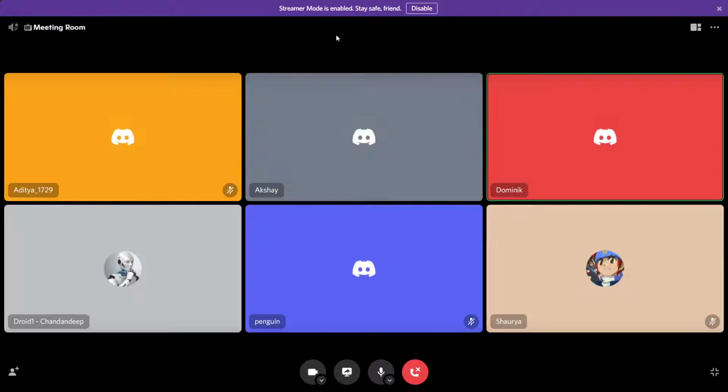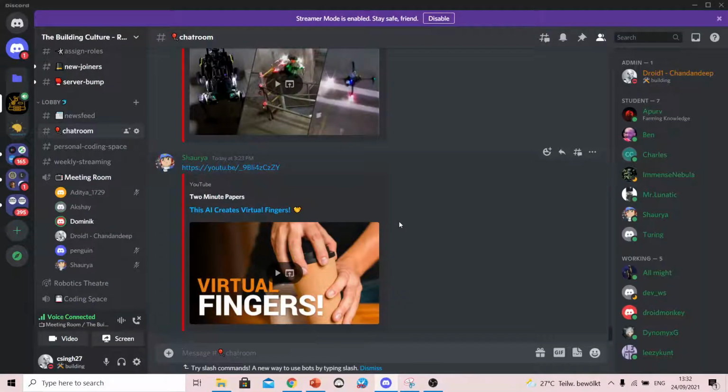Oh yeah, a good question, because today we only talked about tendon-driven soft robots, and there are a number of different ways to actuate soft robots. One of the most important other options is to use pneumatics, and these inflatable robots. I think you've probably all seen that. And then there's also electric piezoelectric actuation. I think I've seen thermally activated metals, for example. But I think the most important ones are pneumatic and tendon driven.